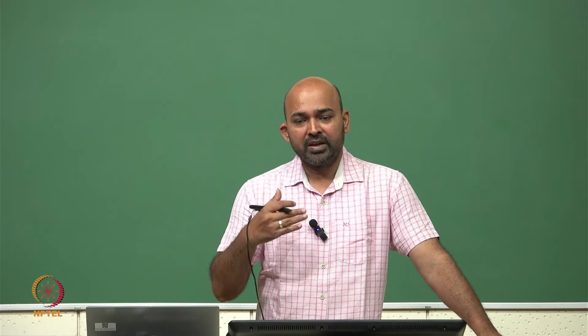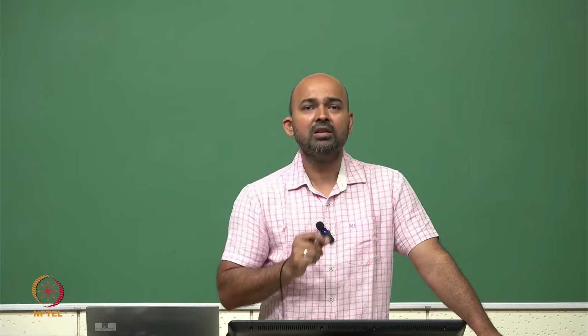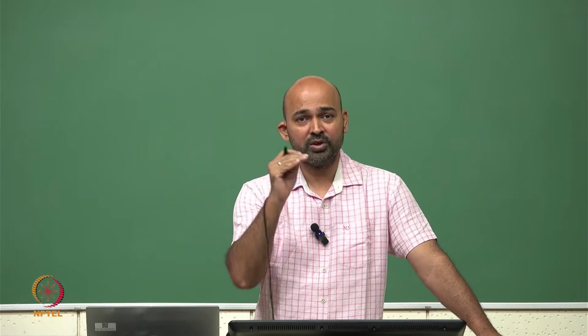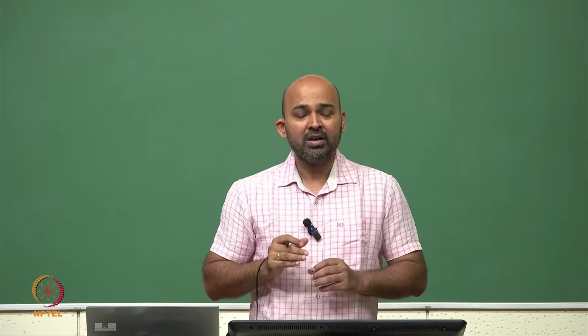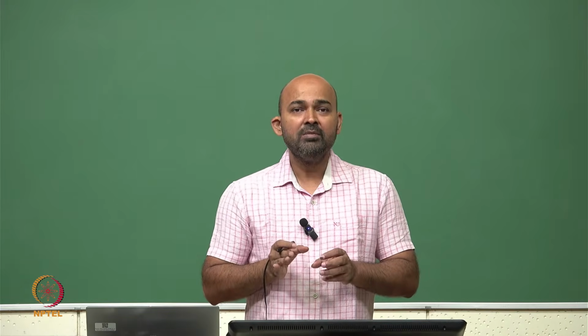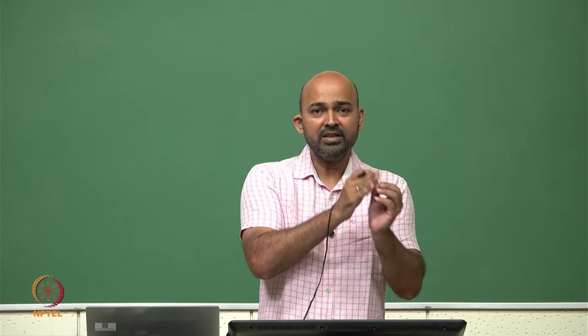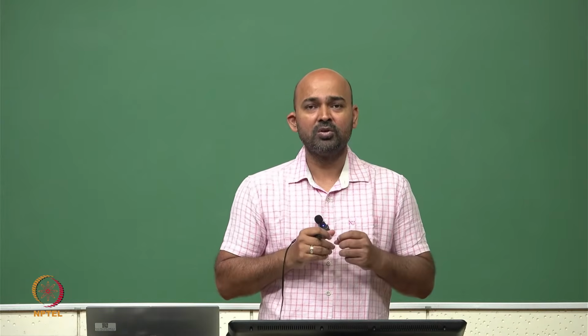So, in DC sweep we are very much interested in very small steps, so that we know exactly how the circuit is going to behave for a very small change in the temperature. However, we cannot make V increment very small, because then for each and every increment SPICE needs to solve the whole circuit.